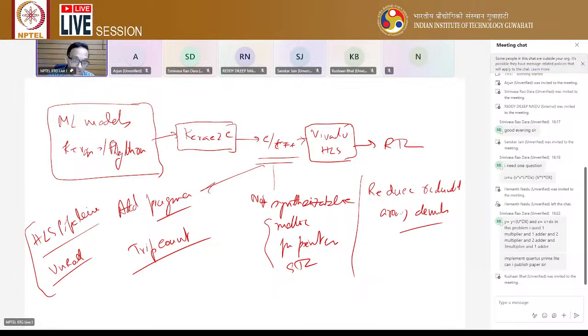There is one more thing I will suggest that is very useful: merge small loops, right? Of similar limits. In the sense that, say, there are two loops and both of them run 100 times, and they have only one operation inside, right? This is the kind of loop which is actually not good. If there are two loops which have only a single instruction, even if you apply pipeline, it doesn't help, right? Because there is only a single operation happening inside.